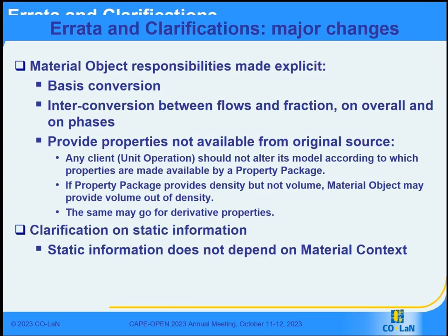As extra functionality, a material object may also support additional services. If, for example, the property package does provide volume but not density, then the material object may perform the required conversion on the fly using basic thermodynamic relationships, just to extend the applicability of a property package. All these things have now been clarified and described in the errata and clarification document.